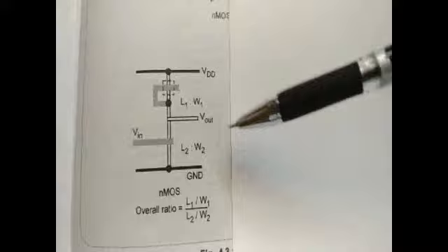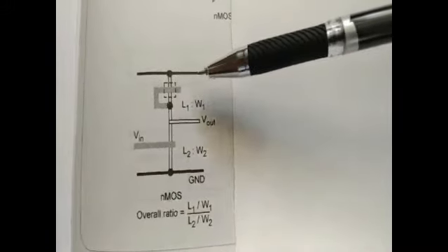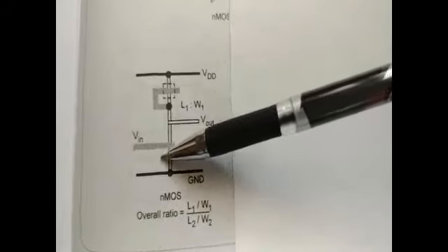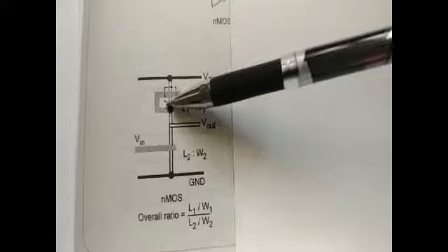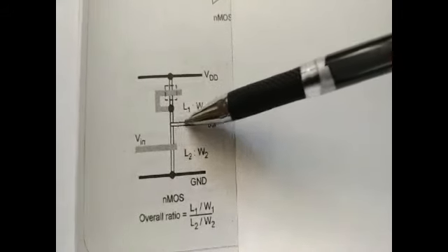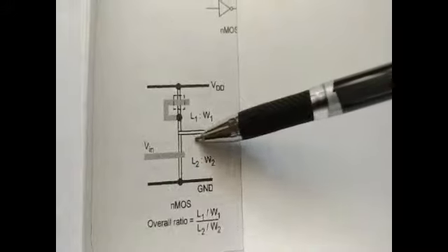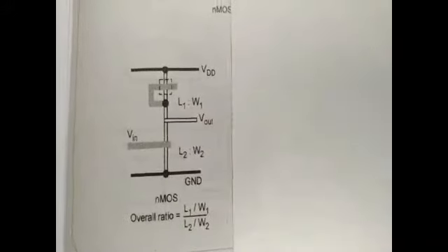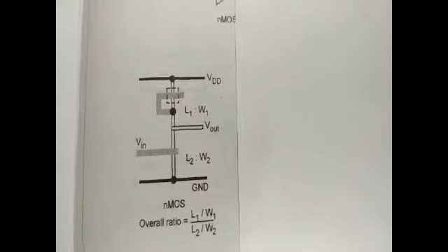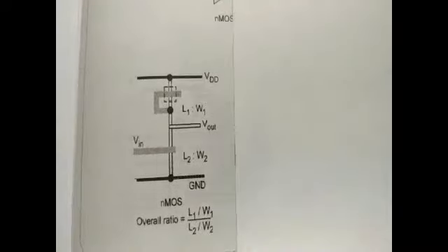Okay, this is the stick diagram structure. We have represented VDD and ground using the metals, and the gate regions are represented by your polysilicon with the dotted lines. The structure with these two, NFET as well as PFET, uses the N diffusion as well as the P diffusion. And another thing, the VOut should also be represented with the dark lines, so that it is for your VOut. Okay, see the structure here. So this stick diagram is an exact replication of your schematic diagram.